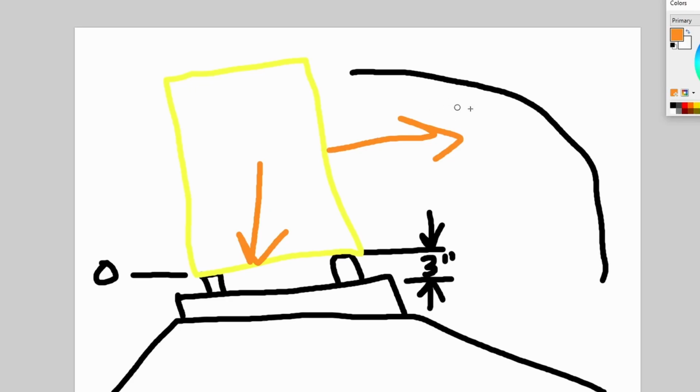Now, it's not typically too much. 3 inches is a pretty decent amount of superelevation, but superelevated track is really common in standard gauge applications where things are running really quick. And it's actually really, really important for those. And it's what sets the speed limits for some trains, because the speed limit for how fast a train can run around a curve is entirely based on the unbalance requirement, which is talking about, okay, well, normally the center of mass of the train is smack dab in the center of the rails in straight track.